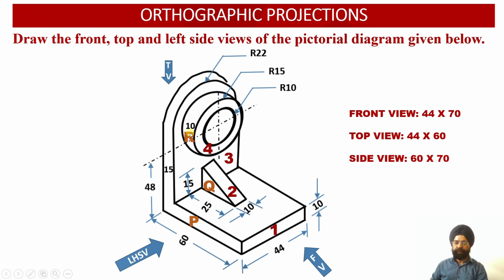Again this surface R corresponds to circular projection. So since this is a circular projection, while we look at the circular projection from the left hand side, only a simple rectangle will be obtained onto the profile plane. So surface R will again be the apparent shape. It will not be the true shape of this particular circular cross section which will be obtained on the profile plane.